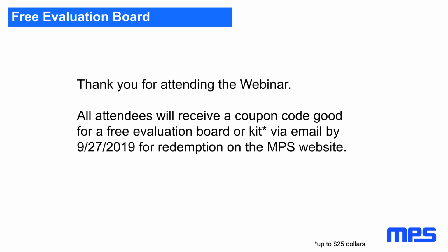You either can use these odd-shaped ones or you can parallel normal ones very close, and they give pretty much the same effect. And you should keep in mind that a plane directly under the capacitor also reduces the parasitic inductance, because inductance is the total integral of the magnetic field created. If you get some of this field away with eddy currents, you reduce the inductance. So the answer is yes, they help, but you could also parallel them to get the same effect.